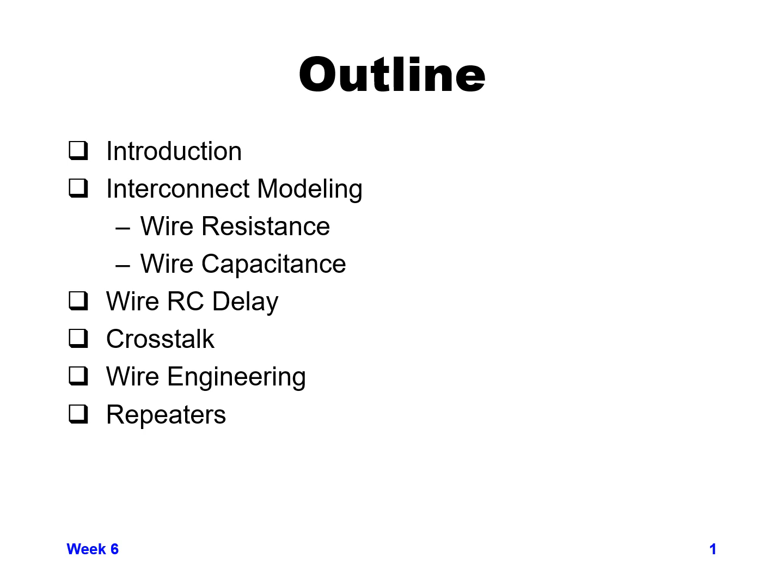Next, talking about what's called crosstalk. That is when wires are routed next to each other and one is switching or both are switching, that they will basically have some capacitance to each other and they will have some effect on each other. As one is switching, it will induce noise on its neighbor.